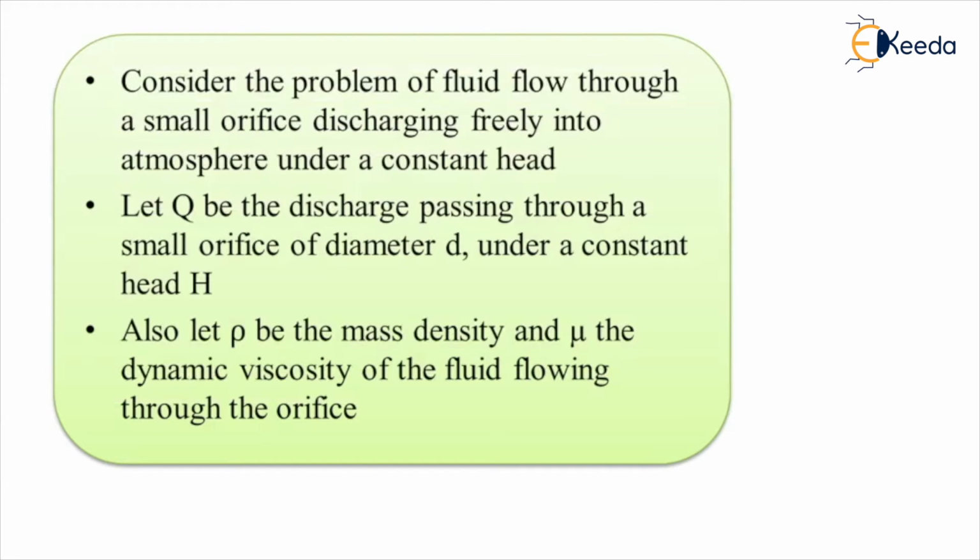Consider the problem of fluid flow through a small orifice discharging freely into the atmosphere under the constant head. Orifice is a hole or opening, especially in the flowing body like pipes. This is the orifice. So let Q be the discharge passing through a small orifice of diameter small d under the constant head capital H. Also, rho is the mass density and mu be the dynamic viscosity of the fluid flowing through an orifice.